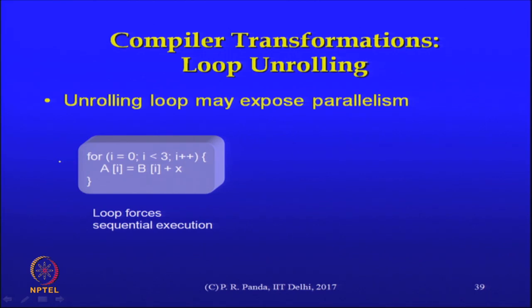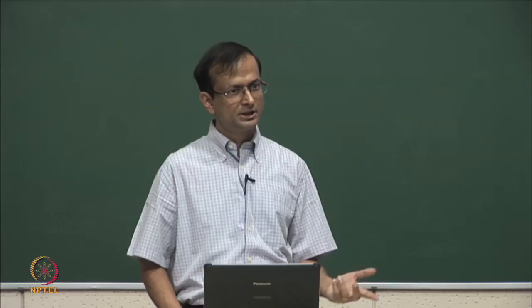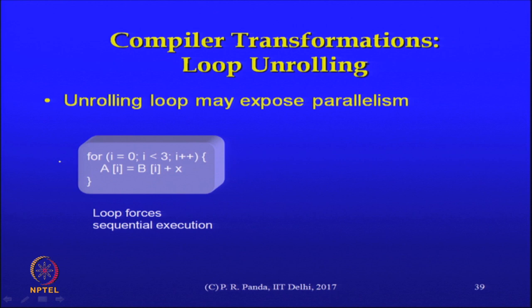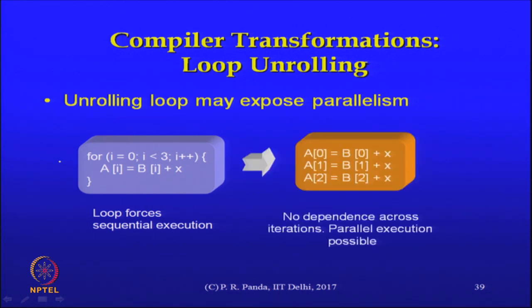First observation is that the different loop iterations are all independent of each other. That can be exploited in many different ways. Independent first of all means that you do not have to respect the order in which the user has written the code. As long as the iterations are independent, we could reverse the order of the iterations and get the same result. But more important is that we could execute all of them in parallel and therefore save time if we had the resources. So, that is the loop unrolling optimization.